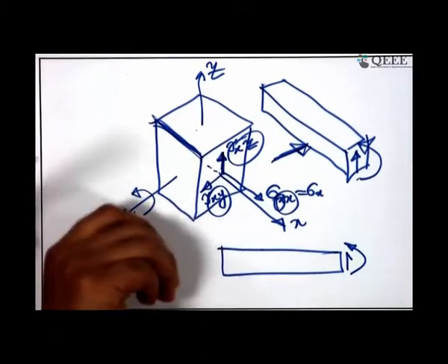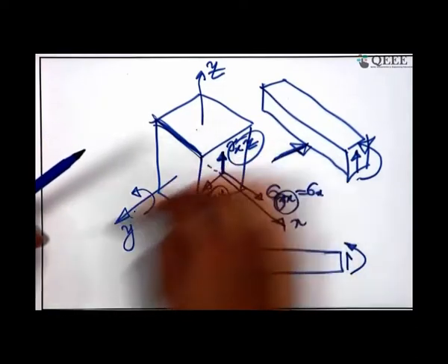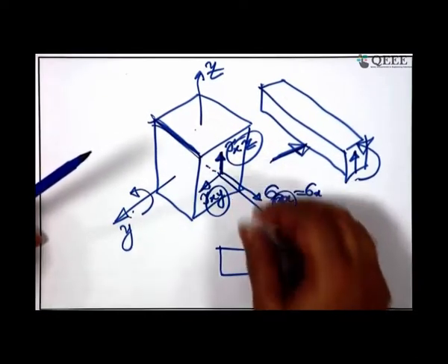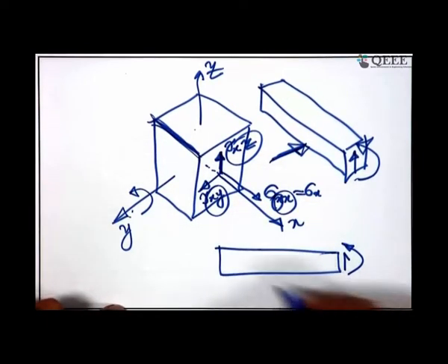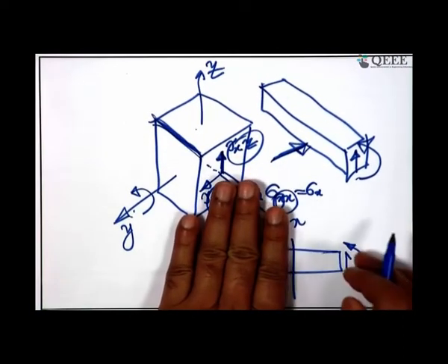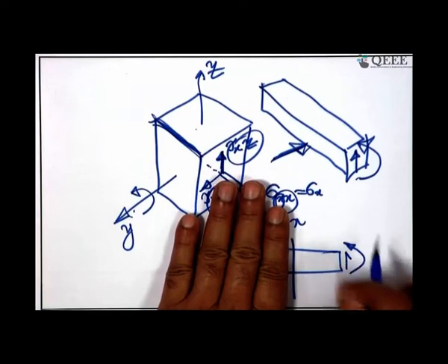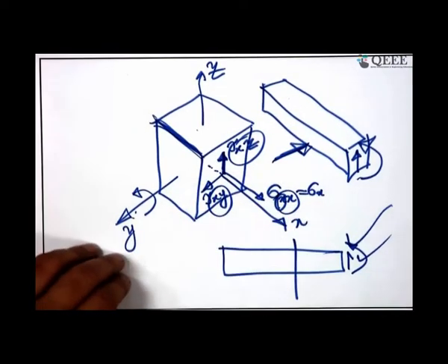If you agree with the positive, this is the famous right handed rule. So, it is a screw. If you unscrew it in this direction, you come out of it. So, this y is the positive direction. You can see it here. If you unscrew, you come out in this direction. This is positive. If I consider a section here and consider this part, on the right of it, right up is positive. This is a sagging bending moment and this is the right up shear. Ideally, this is the sign convention you should follow to be consistent with further literature in higher studies or any other research materials.